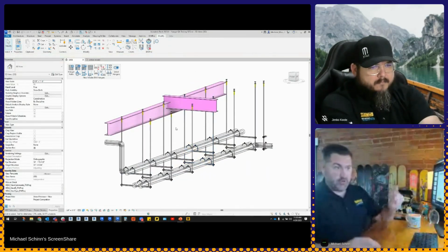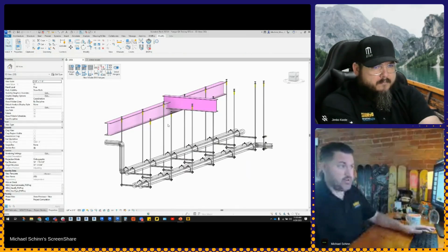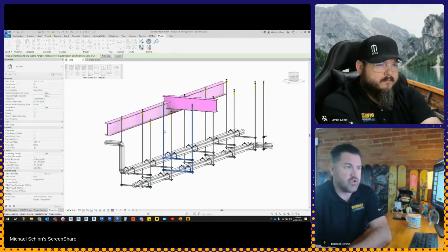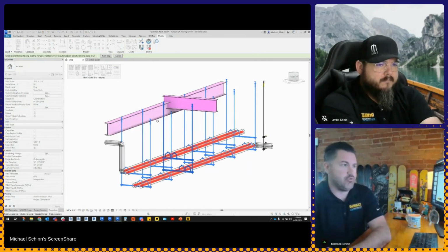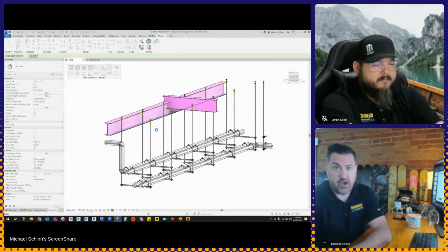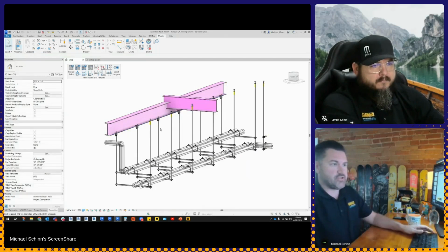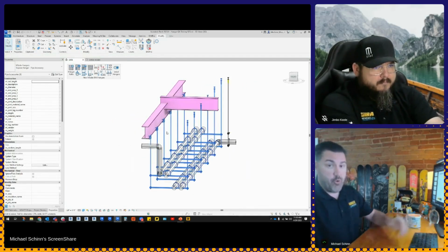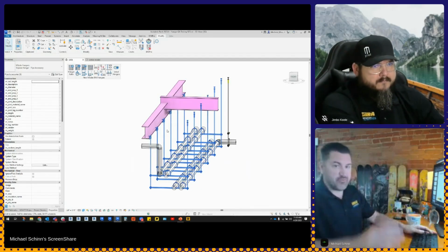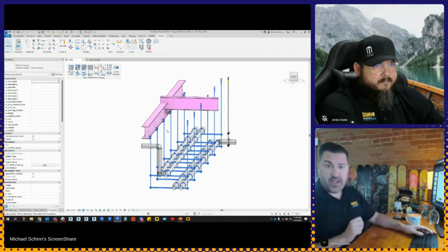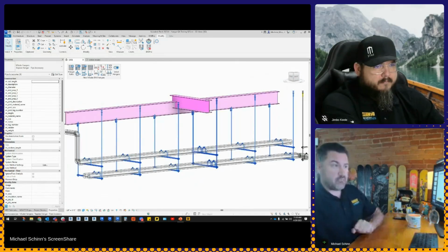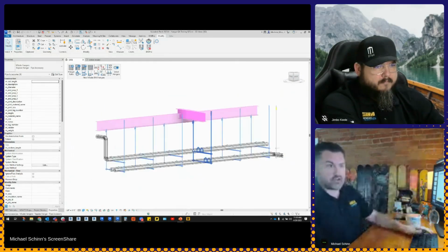Well, we can go through the process and move stuff around, but I want to use this command here, attach hangers to beams. Click onto one hanger. Again, it grabs that whole run. I click next, select the beam, and it's going to automatically reach and connect all of those to that. We've got some more improvements coming with our next release about controlling which side of the beam it actually goes to, coming out soon. So real easy being able to connect to that structure.